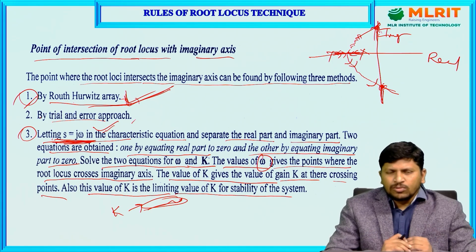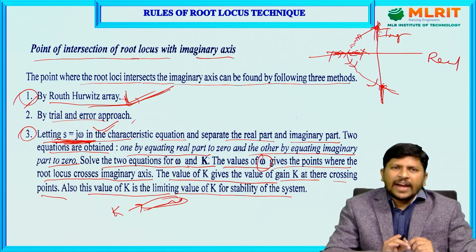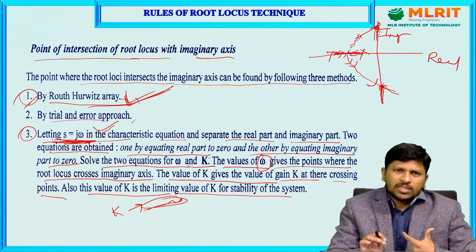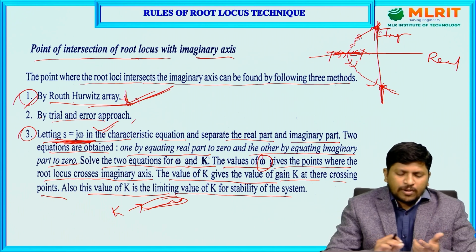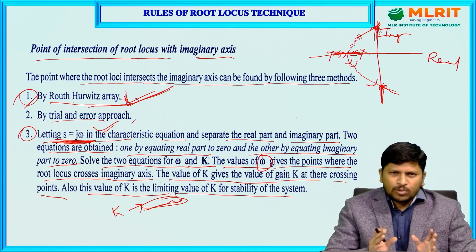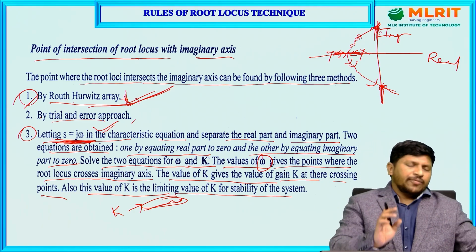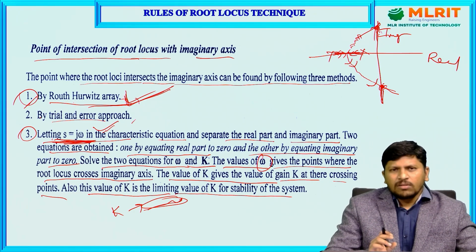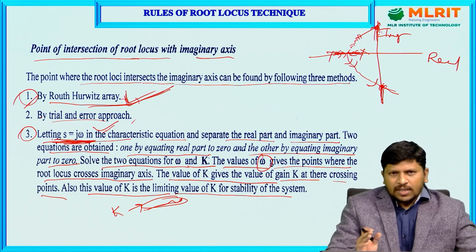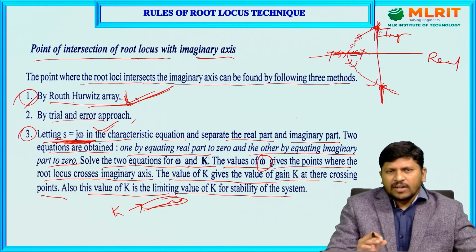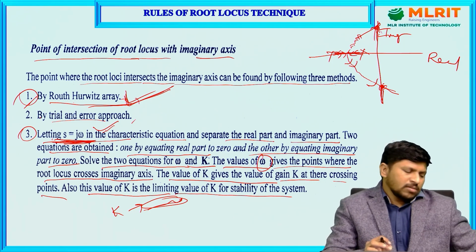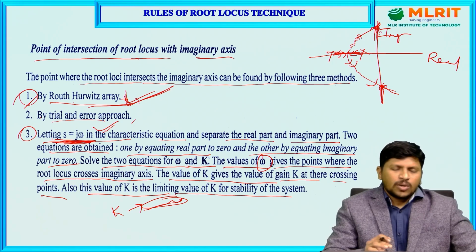We need to use a normal graph sheet and draw the root locus on that graph sheet, and also locate the roots on the left side or right side, so it is easy to identify or follow. For higher order polynomial equations or higher order systems, the root locus technique is very useful to locate the poles on the real axis in the S-plane. Okay, these are the rules.